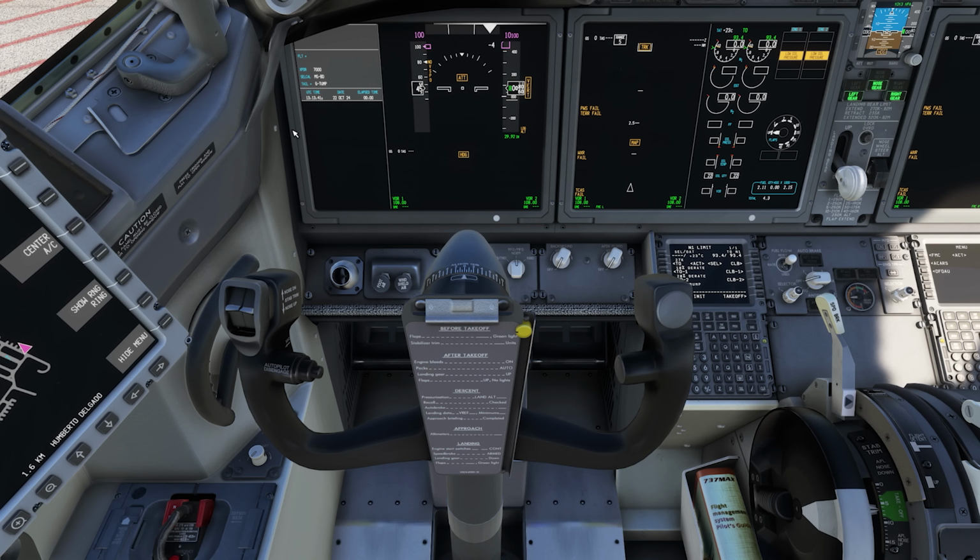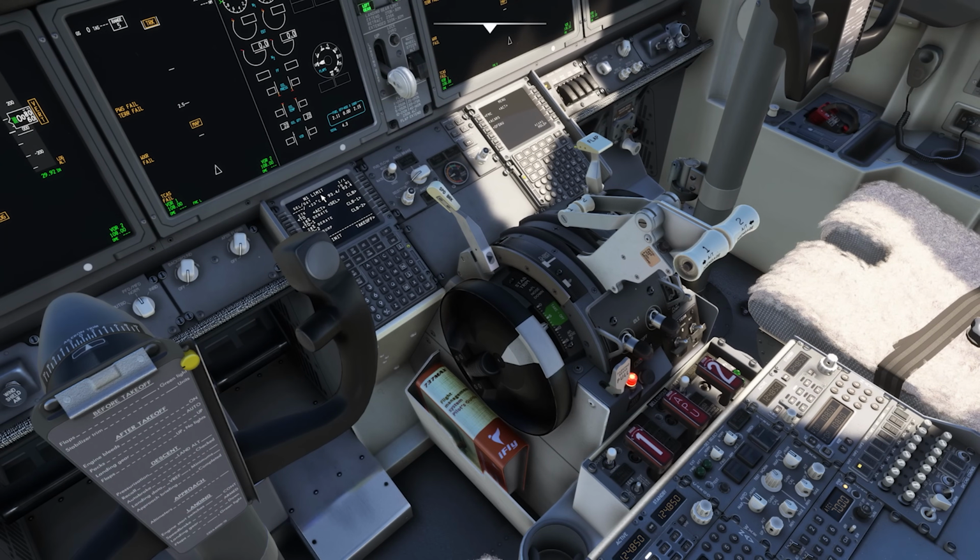One of the major changes with the flight controls is actually with the speed brake system. The speed brakes are now completely fly-by-wire, so they've replaced the traditional units and now have an electronic fly-by-wire system for the spoilers and a spoiler control electronic unit. That saved a lot of weight as well, and it's allowed for some additional features with this speed brake.